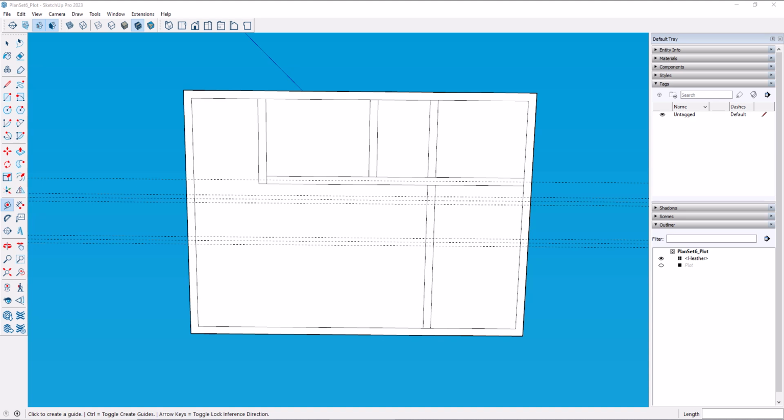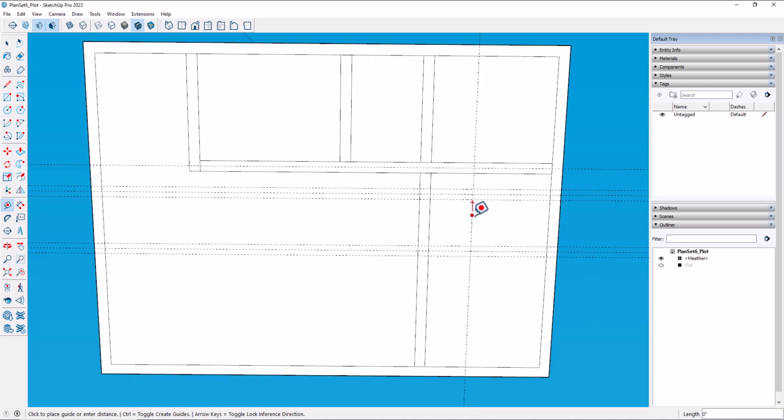Lastly, this isn't exactly in the footing blueprint, but based on the walls, we're going to simply go from the right over to the left, making sure that our guide is red, and we're going to go 8'3", and this is going to be that kind of bathroom wall. And so we'll go 6 inches on each side.